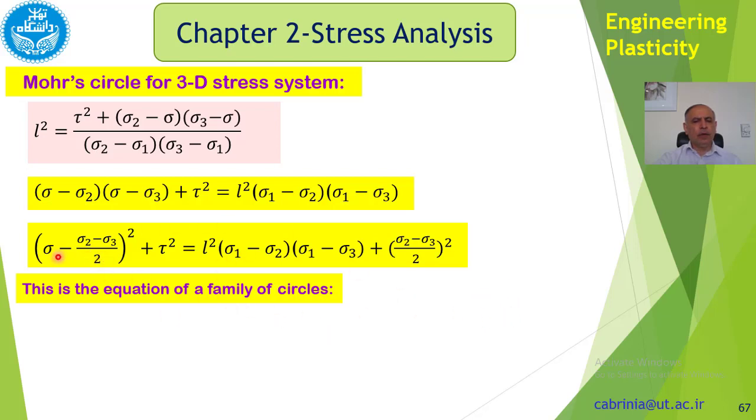Okay, so I've got sigma squared plus tau squared. Also, this is a number, sigma minus a constant number. Of course, L is not constant. L is not constant because L is the direction cosine, and the direction cosine can change depending on the angle. If this is cos alpha, then alpha changes between 0 and 90. Therefore, this term changes. So we'll see what happens.